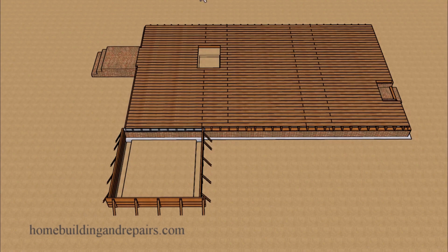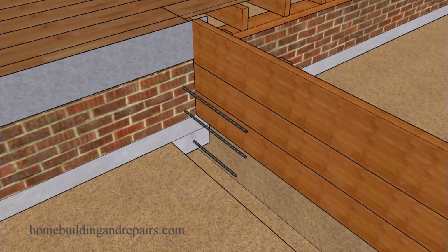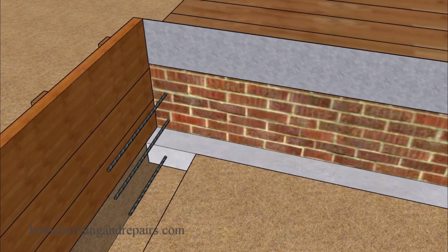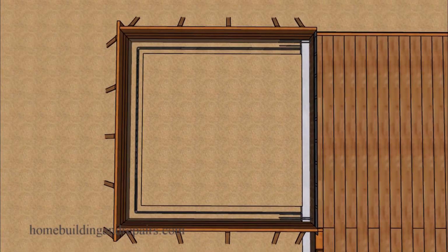However, if I was going to install a wood framed floor, then I would need access to the area underneath here. Next up, let's go ahead and take a look at some dowels that might be required by a structural engineer and the location along with the depth of how far they're going to go into the existing foundation will be provided by the structural engineer. Now, on a brick building like this one here, you might be required to modify it a little differently, and I will provide you with a little more information about that towards the end of the video.